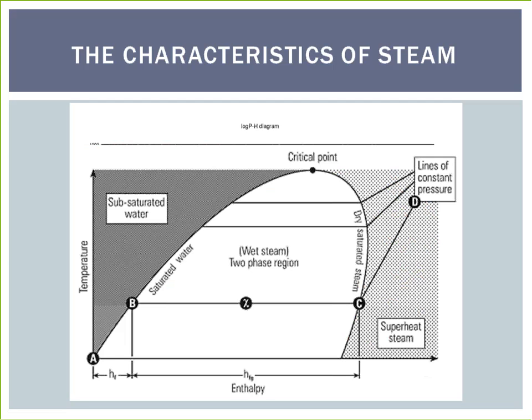As water is heated from 0 degrees Celsius to its saturation temperature, its condition follows the saturated water line until it has received all of its liquid enthalpy. If further heat continues to be added, the water changes phase to a water vapor mixture and continues to increase in enthalpy while remaining at saturation temperature. As the water vapor mixture increases in dryness, its condition moves from the saturated liquid line to the saturated vapor line. Therefore, at a point exactly halfway between these two states, the dryness fraction is 0.5.